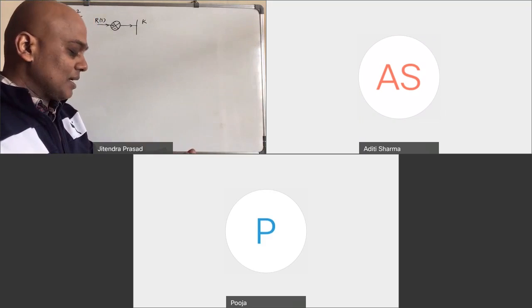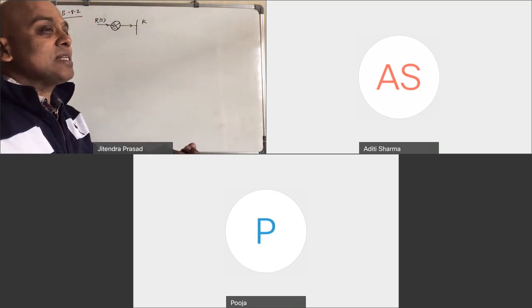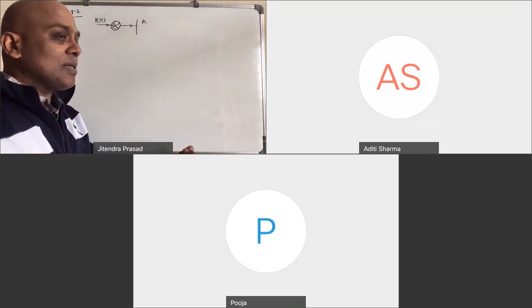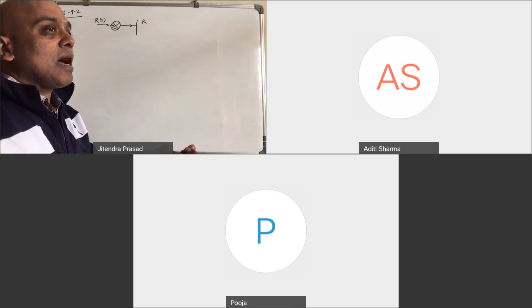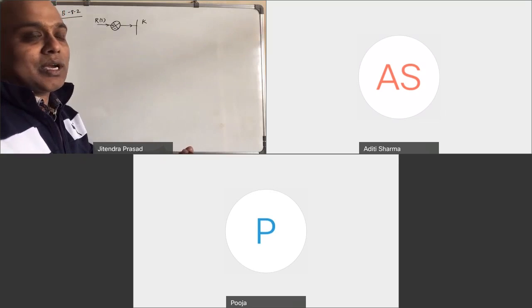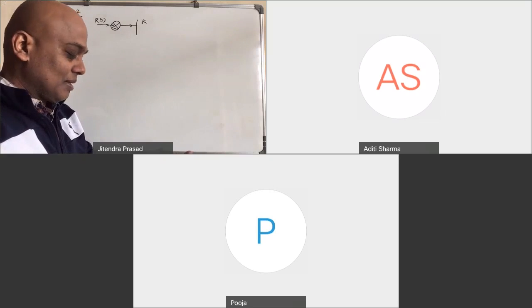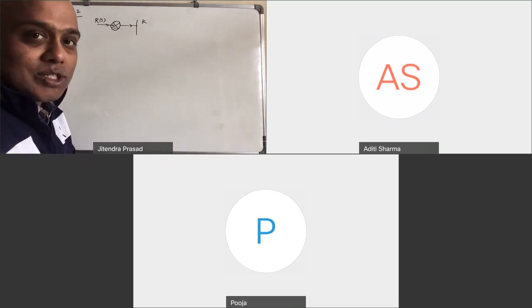And when you say settling time 2 seconds, that fixes zeta times omega n. But overshoot is 20% or less, and that really means zeta may have different values. So accordingly, omega n may also change. So you have quite a range of values. Got it? So it is not one solution. It could be many solutions.